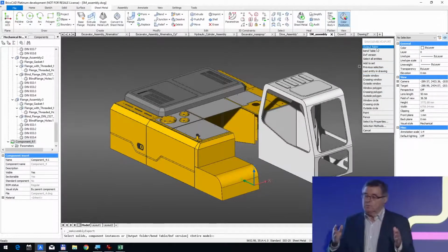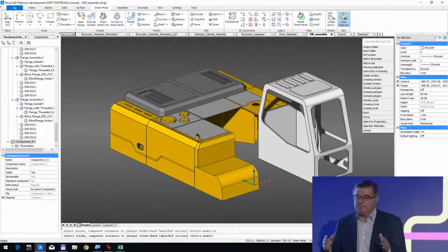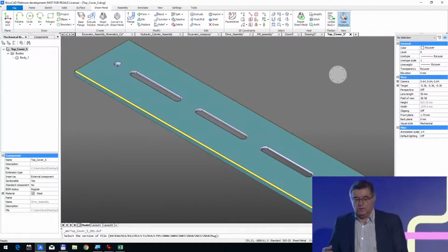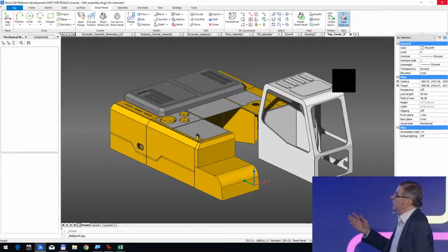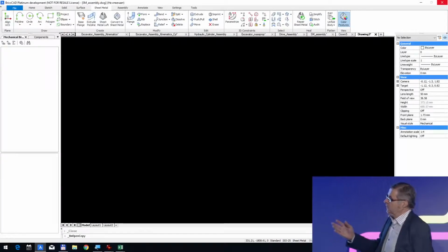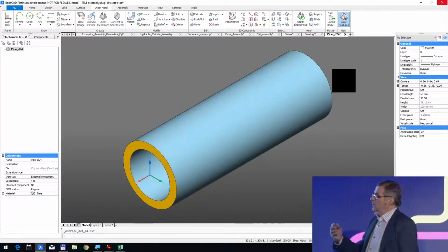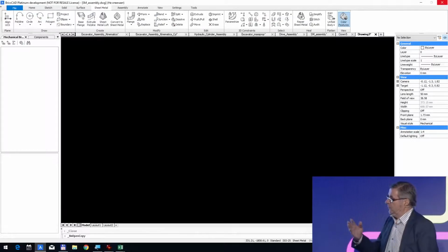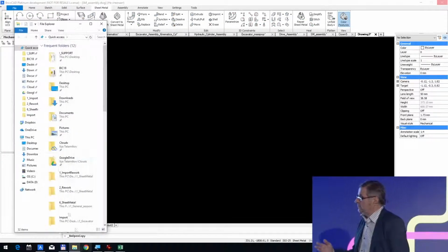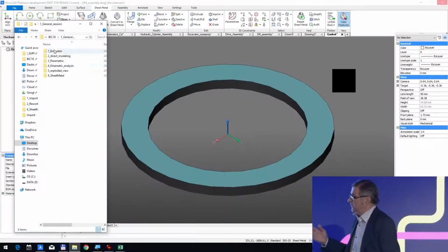So we will complete the second goal, produce the document and material for manufacturing. So we will launch the batch application that will examine all the parts, sort the parts between sheet metal and non-sheet metal. The sheet metal parts are automatically unfolded.